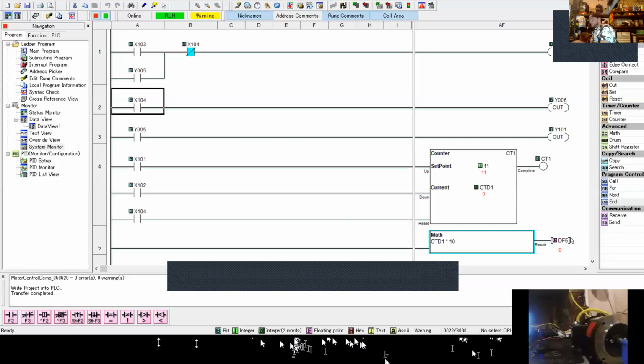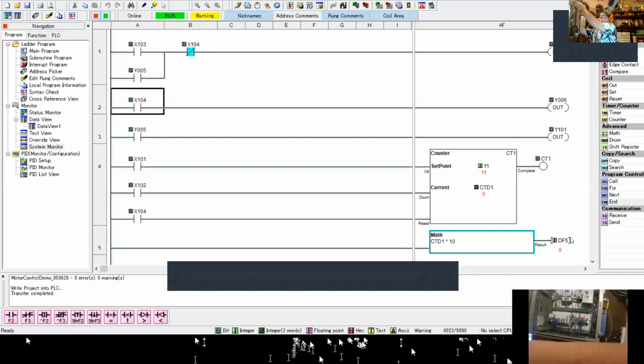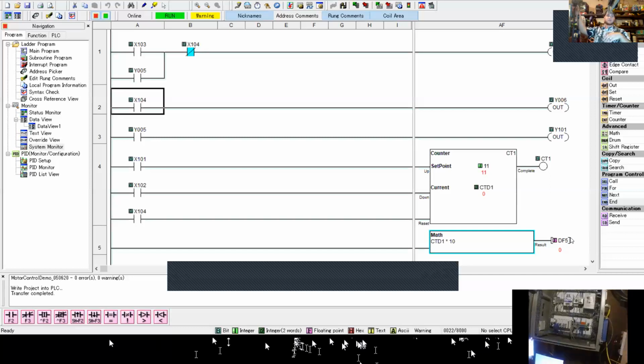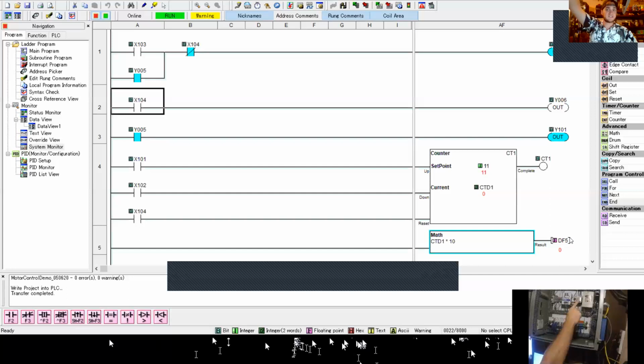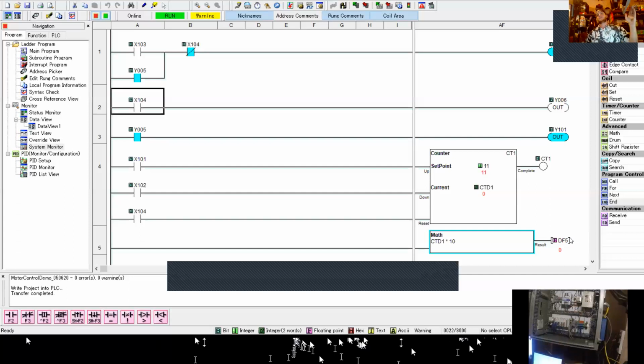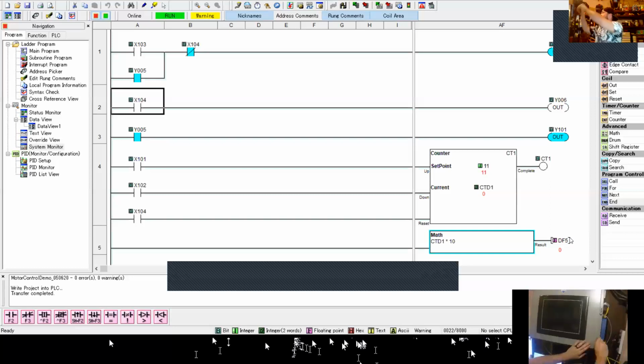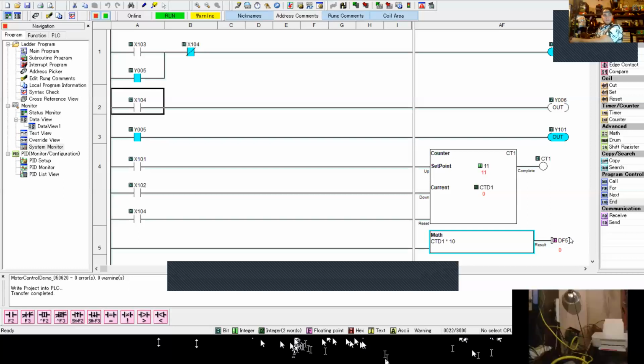I'm going to change your camera view again. And I'm going to hit the start button. Okay. I don't know if you guys heard that ka-chunk, but there's a nice hefty thump that happens when you do that and the contactor gets pulled in. And then the status light on the VFD changed. Okay. So now I know my system's happy. I think everything's good to go.